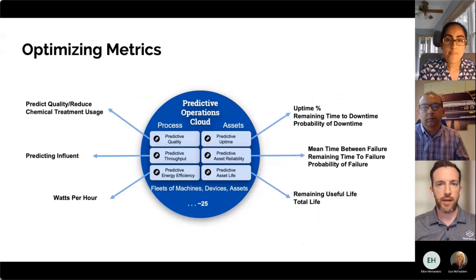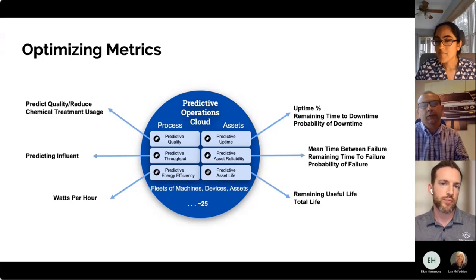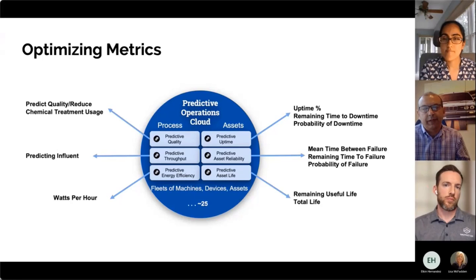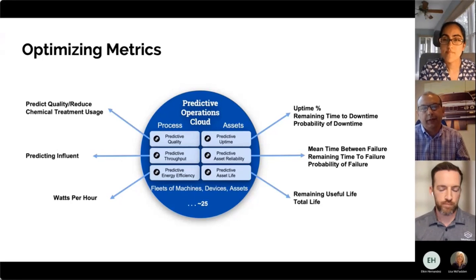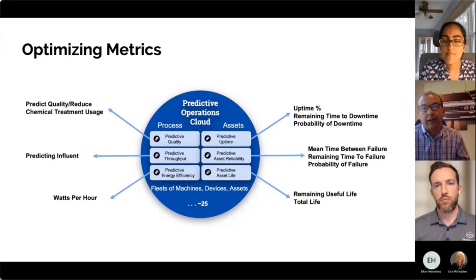Yeah, absolutely. And Kamel, you said it in your intro, people or organizations used to just ask what's going on now, but now they want to know what's going to happen. So can you talk about how AI ML can help? Sure. Today many of our customers are still doing maintenance based on a calendared approach. And the people near the advanced end are looking at least at runtime hours. One of the challenges there is getting the runtime hours from the SCADA equipment into the CMMS systems. And runtime hours are much better than a calendared approach.